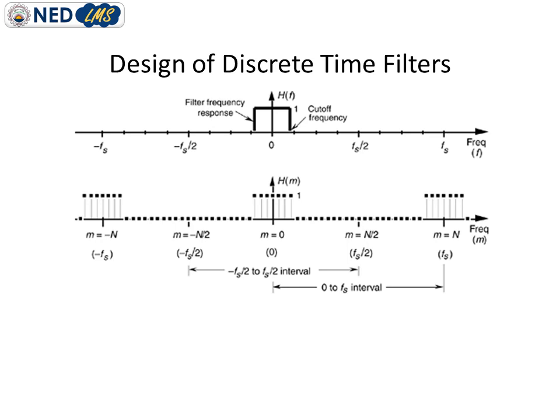Now the next step after selecting the desired frequency response is to determine the filter coefficients, or in this case we have to determine our low pass filter's time domain coefficients, which you can say is the impulse response.